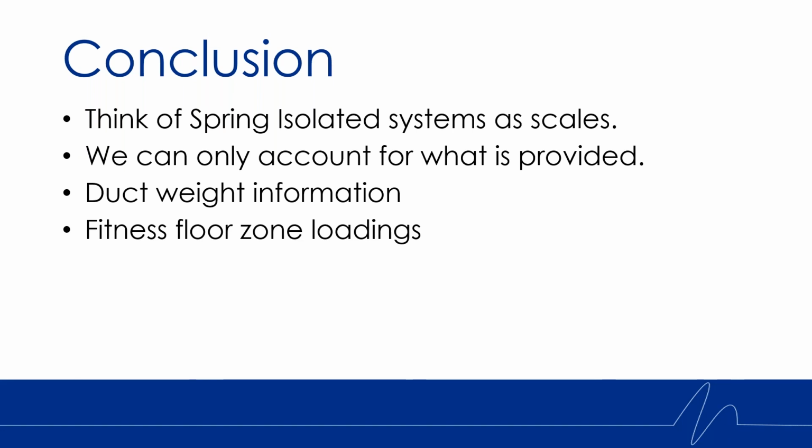And when it comes to the fitness floor zone loadings, the key items we would like to focus on are anything that is exceedingly heavy and stands out amongst the rest of the pieces of equipment. So if the majority of the equipment weighs in a range of 200 to 400 pounds, and you have one item that weighs, let's say, 800 to over 1,000 pounds, we would like to make sure that we coordinate the location of that to ensure that the springs are selected properly.